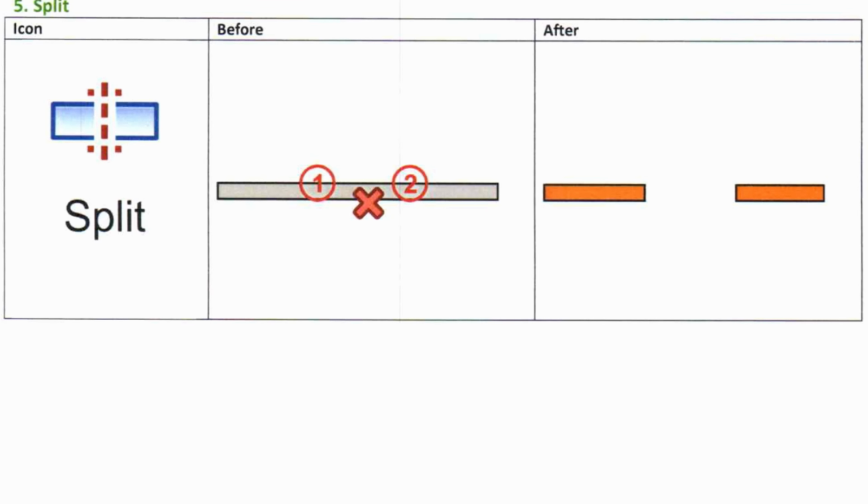Important notes. Tool must be selected before clicking the component. Do not use Split to create openings for doors or windows. Use hosted components instead. Splitting walls may affect room boundaries. Use room separation lines if needed. Best practices: use Split for geometry control, not for hosting logic.